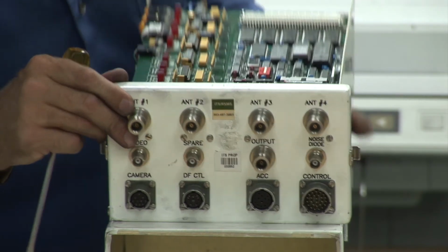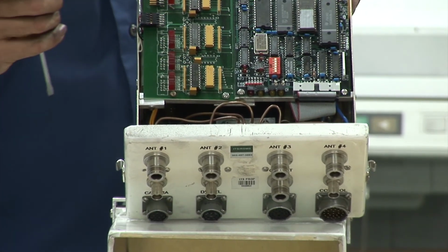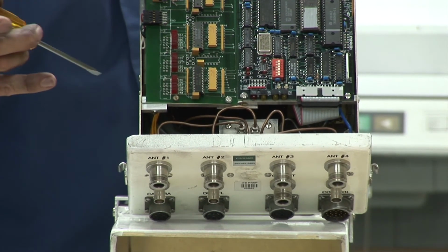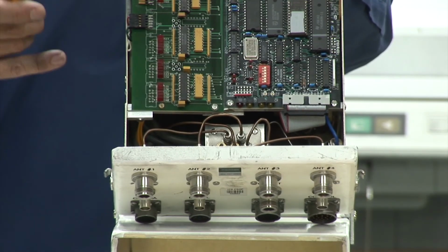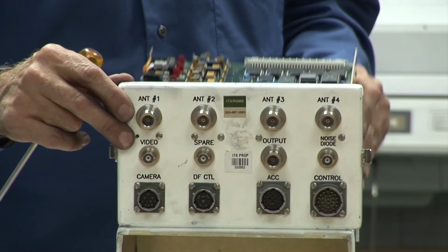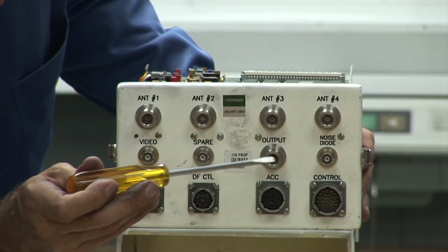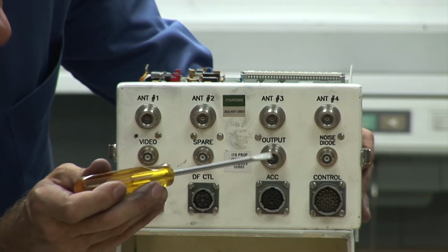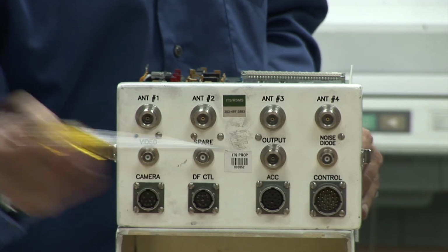And then, just under the circuit board now out of the field of view is a YIG, a low noise amplifier, actually a set of low noise amplifiers, also a set of fixed band pass filters in addition to the YIG, and finally, after all of that processing, the output port, which is located right here. And this is the output port that then connects this into the rest of the measurement system.